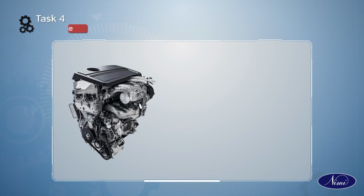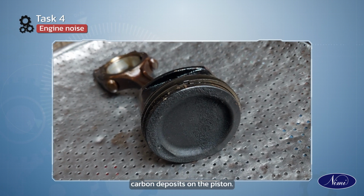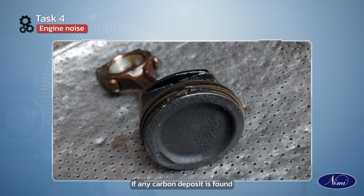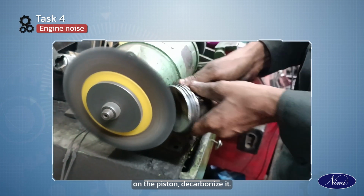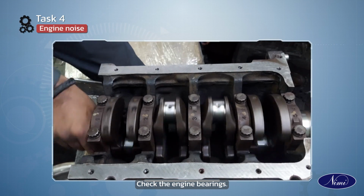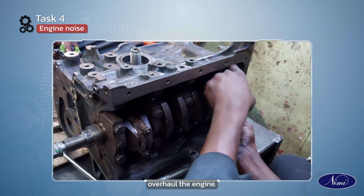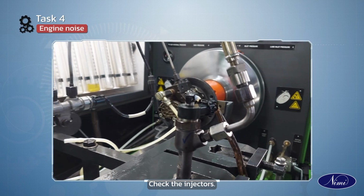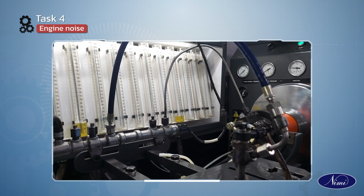Engine noise. Check the quality of the fuel. If the quality of the fuel is not good, replace the fuel. Check for carbon deposits on the piston. If any carbon deposit is found on the piston, decarbonize it. Check the engine bearings. If the engine bearings are worn out, overhaul the engine. Check the injectors. If a defect is found, overhaul it.